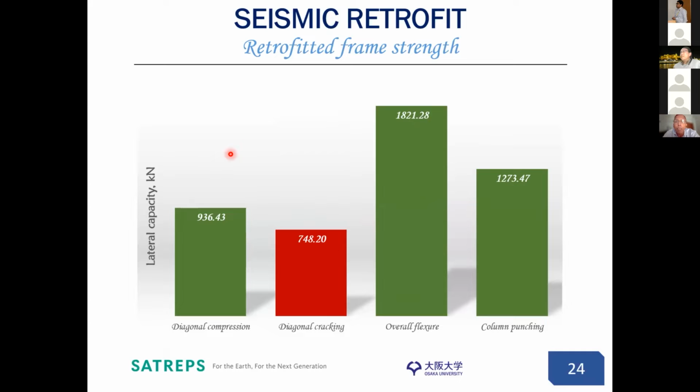So this can also be a trial and error method based on if you have multiple deformation limit requirements of the retrofitting technique. After retrofitting, if you calculate and find that your retrofitted wall fails in a defined mode and other capacities are higher, you might be able to increase that range. But on the first trial, it's better to assume the worst case, which is 1.27, because in our case, we are not retrofitting enough that this will go to column punching. So we ignored that one. Anyways, this is a trial and error process. So if you make a mistake and find something else happen, just go to the process and recalculate it.